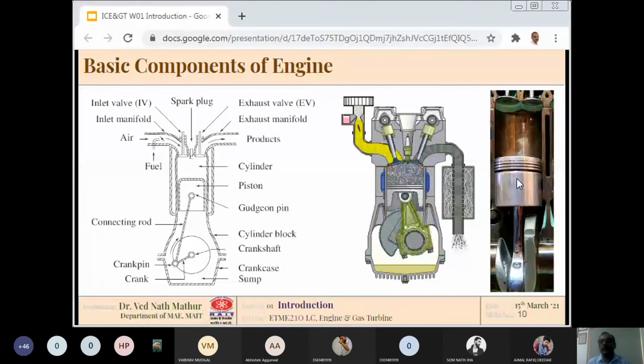So rubbing is only between the piston ring and the cylinder wall, so that after some number of cycles, say after 1 lakh kilometers, or your car manual has those details on after how many kilometers you should replace your piston rings, you can replace the piston ring. You need not replace the entire piston. Once the rings get worn out, they can be replaced.